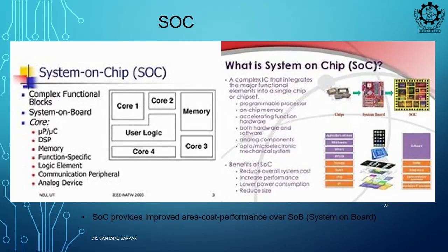So, this is actually this modern IC. What is this modern IC? They look like this, looks like this SOC. You may have heard this term, system on chip. Okay. Previously, we were having system on board. On the board, you have several discrete components, discrete ICs connected on the PCB, printed circuit board. Now, the same functionality we are trying to bring down from the board itself into an IC, that is a system on chip.